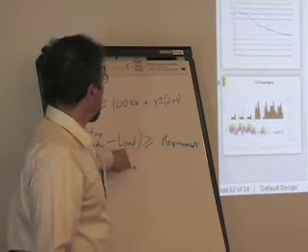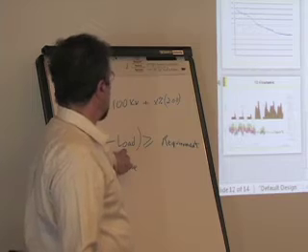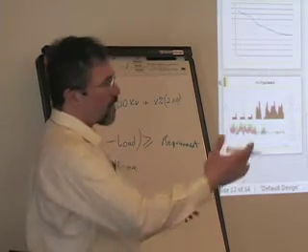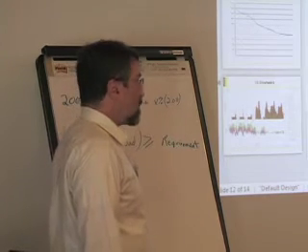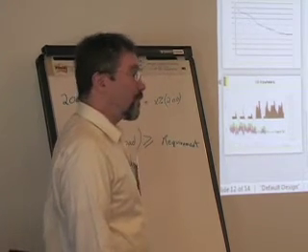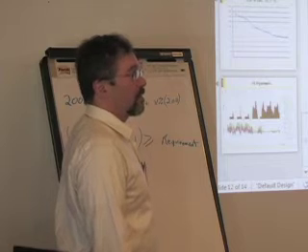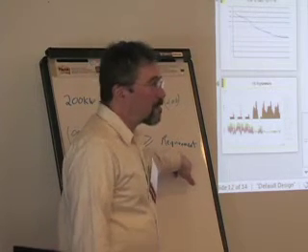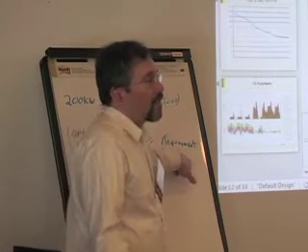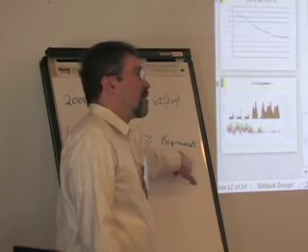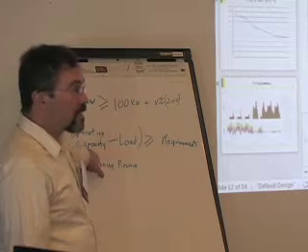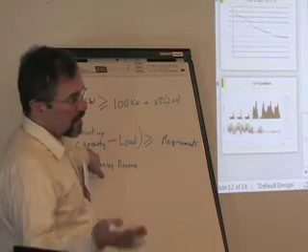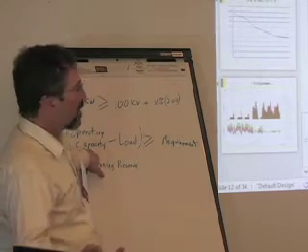So when you talk about operating capacity minus the load, in the example you gave, because it's wind providing the operating capacity, this is what's going to your secondary load. And that counts as spinning reserve, and it has to be greater than the spinning reserve requirement. If the operating capacity were being provided by diesel, it typically wouldn't be going to your secondary load.